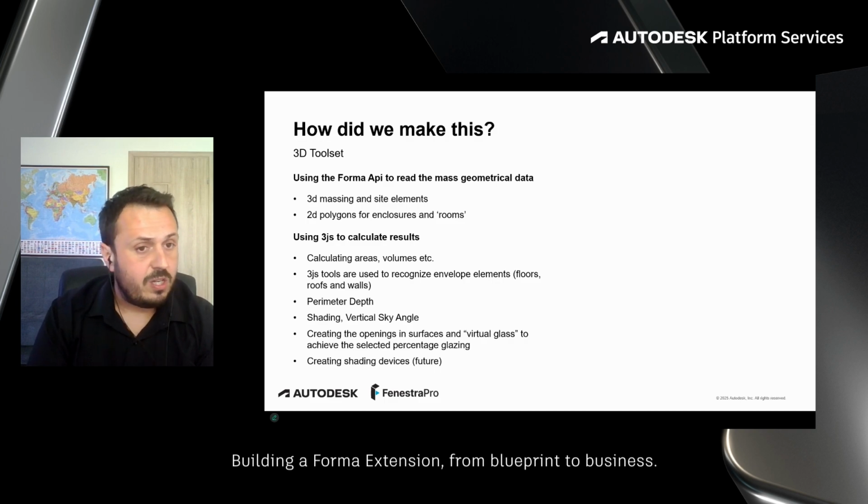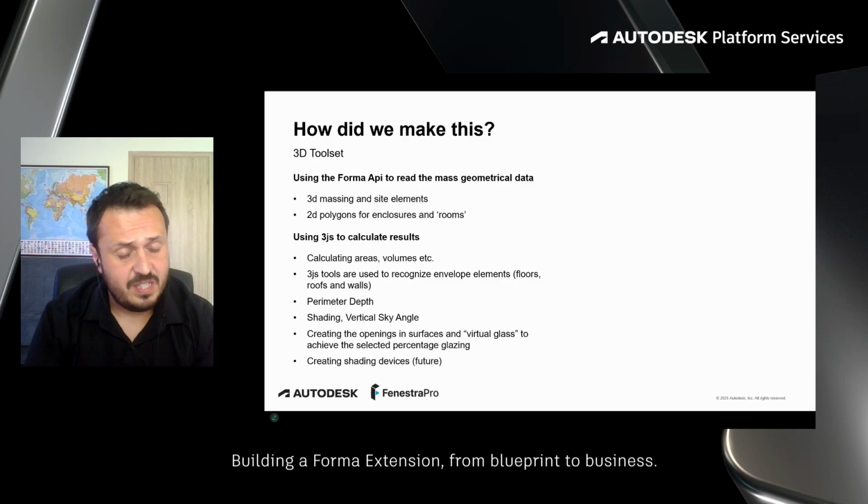For that reason, we need to create what we are calling virtual elements on our side. So basically, we are creating virtual walls. These objects have the same geometry as, for example, the analytical surface. They still don't have thickness because we don't need that at this stage. So we are taking the surface points and that geometry and providing it to the host wall.